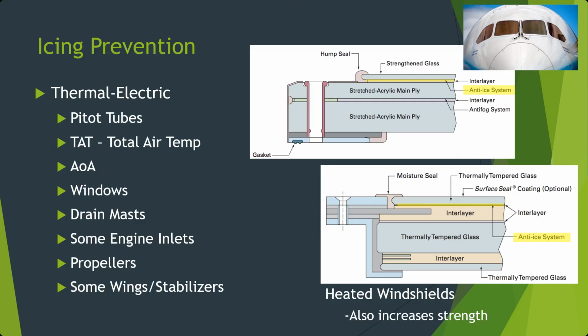There's a very strange effect when you're looking through these windows: oftentimes you can tell when the anti-ice cycles on and off. It turns on, heats to a certain point, and then there are temperature sensors embedded in the glass. So when it gets up to temperature, it shuts off the flow of current to prevent overheating. And so it'll cycle on and off, and when the current turns on, you see a slight blurring in your view, like it makes your eyesight slightly blurry through the window. Then it shuts off, and it goes back to being clear.